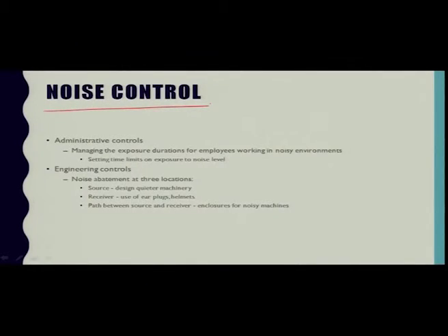The combined effect of different sound intensities can be summarized as a noise dose, which is a percentage value that combines several noise components into one measure, such that any value above 100% exceeds the OSHA permissible limit.